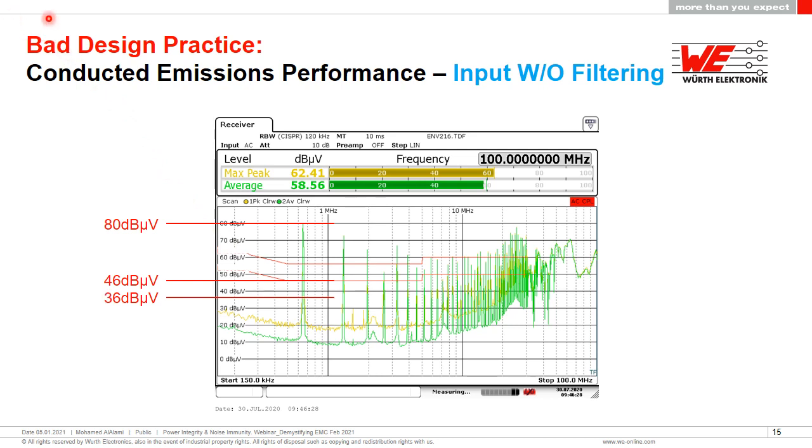And what we will want to do is have an extra 10 dBs of margin, just to be on the safe side, giving us sort of an overall 44 dB of insertion loss or attenuation at that 630 kilohertz fundamental frequency. So we can clearly see on this